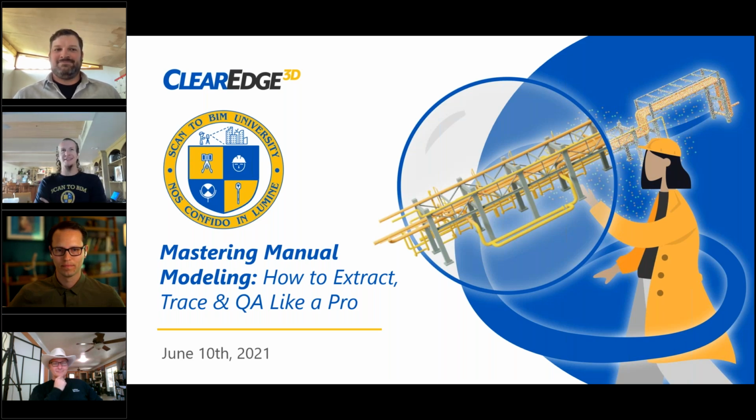Dustin's got a project in process here, and we were talking about how it's kind of fun in laser scan because the reflectance of the surface has an impact on the intensity value. So any kind of changes in quality of a surface, like for instance a little bit of moisture, will make the surface more reflective for the laser, and so you'll get less of a return back. So you can see things like water content in materials on a surface. Like if you've got a basement wall and you've got some leak issues, wait till it mostly dries out, run a scan, and you'll see actually where the spots are that you've got moisture penetration coming in through your basement wall. So there's some fun stuff there.